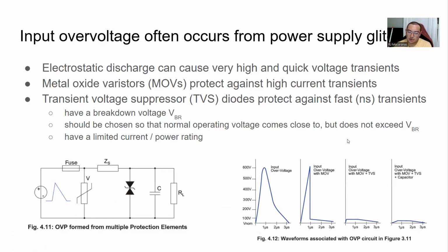So you just need to understand what your DC to DC converter is being fed in order to protect against it. I'm guessing some of the systems that I've designed just don't have these MOVs, probably because we don't need them, but you just want to understand what your source looks like and design accordingly.